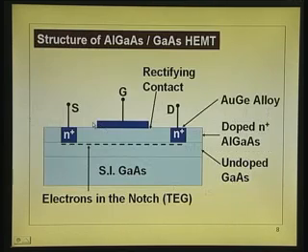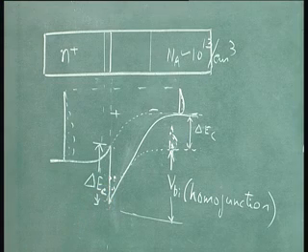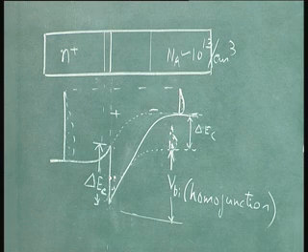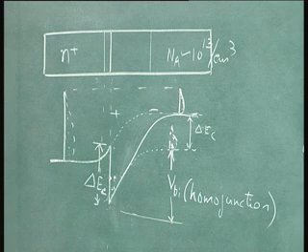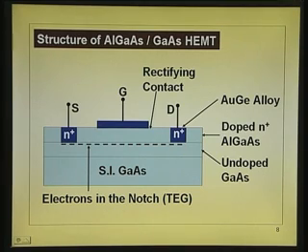Okay, now comes the application of this heterojunction. All that you do is make use of this junction, so that you can lock these electrons in that notch, and make use of them for transport. So, in a heterojunction transistor, which you can call a high electron mobility transistor, HEMT, that is what Fujitsu calls a high electron mobility transistor. In fact, this transistor you can see has got